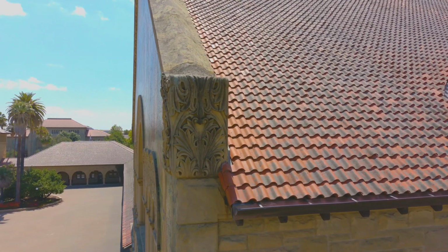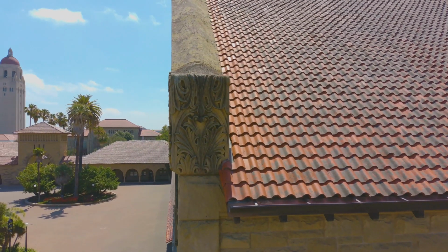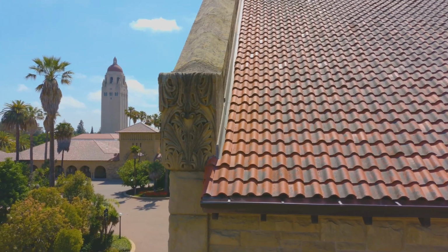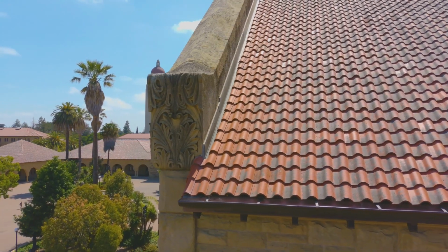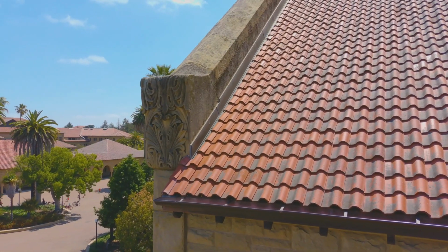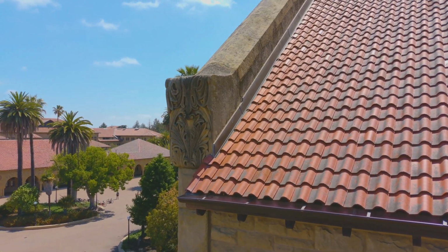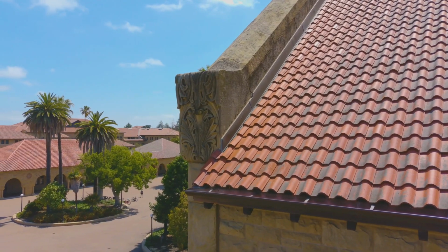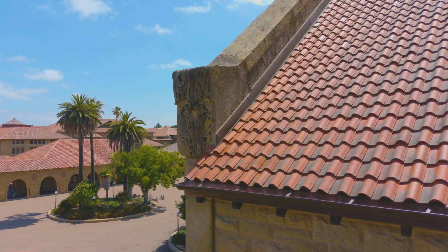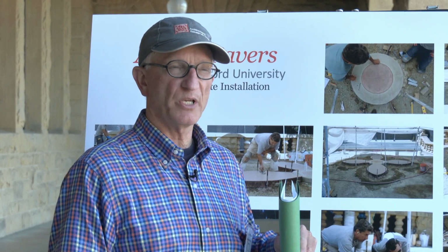When we re-roof and we have supplied new tile, we mix them in with the old at random so that the differences are not noticed. And then the membrane is replaced and the roof goes back. And so what's wonderful about the clay tile is it can be reused and reused and reused. And we really haven't seen much deterioration even from the beginning of the tiles.